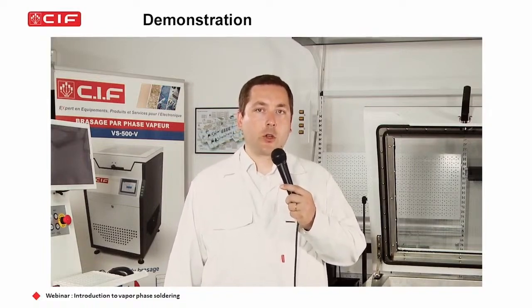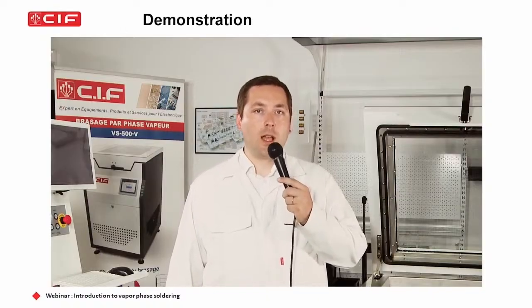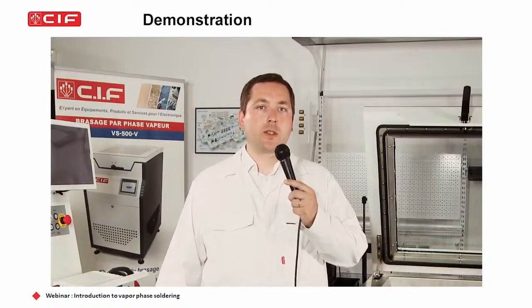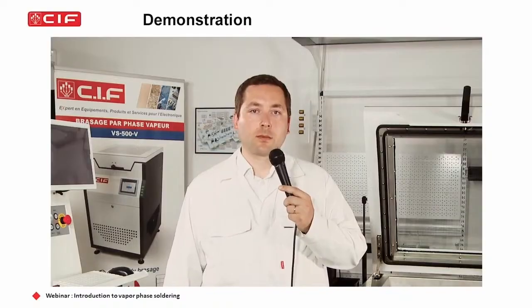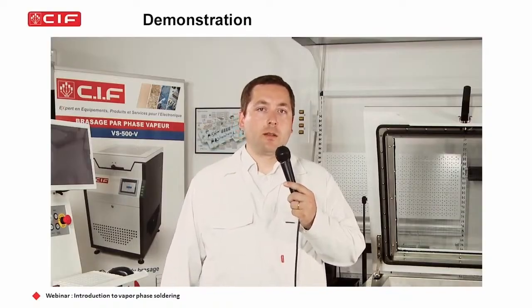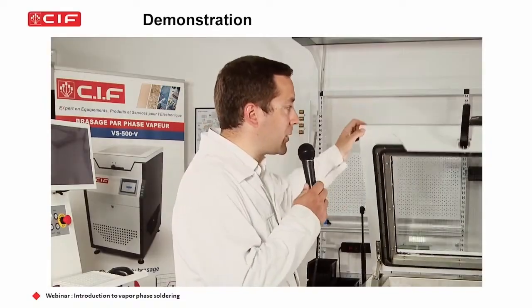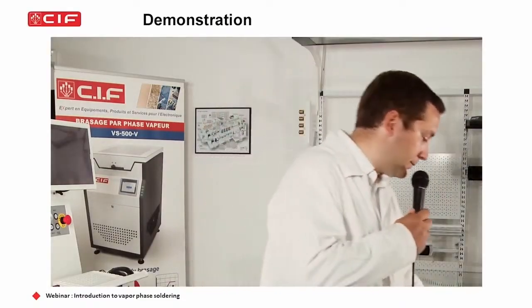Then we have the time vacuum and fan. These are the settings for cooling and Galden recovery. It means the longer time you set, the more Galden you will recover. So we can now close the lid and press the start button to start our cycle.